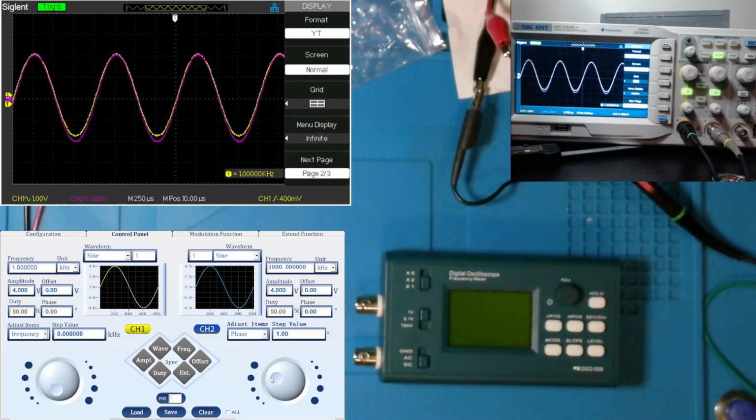So that's pretty cool. And if you're used to looking at Lissajous patterns on your oscilloscope, then you can most definitely spot phase difference between your AC waveforms, and that can be potentially good with troubleshooting, especially audio alignments and stuff, where your waveforms must be out of phase in order to not cancel each other out. Just something to think about there. But what about component troubleshooting?